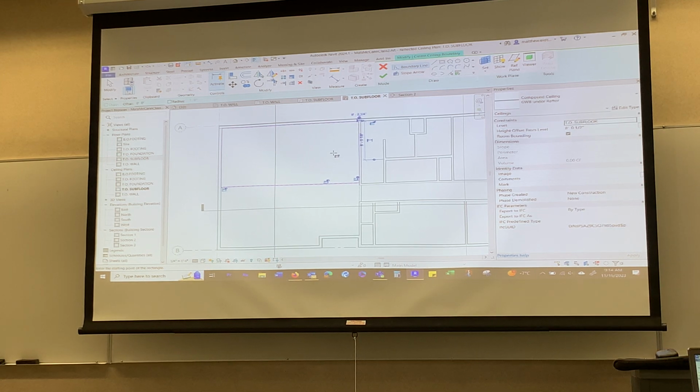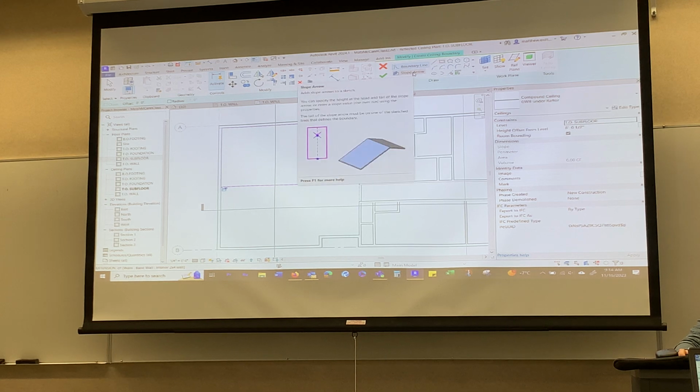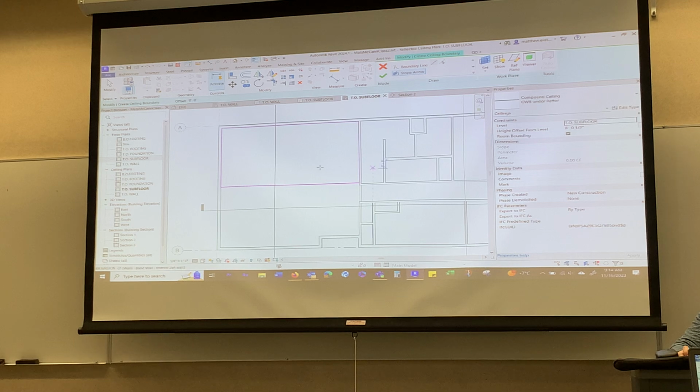Okay, now rather than leaving like I just did to show the flat ceiling, don't do that. Don't check the finish yet. So I just drew that ceiling in to my annotate line using the rectangle tool. I'm gonna go to slope arrow now. You can leave if you want and then go back and select the ceiling just like you would with a floor and then go edit boundary. You don't need to, you can do it right now. I can click slope arrow.